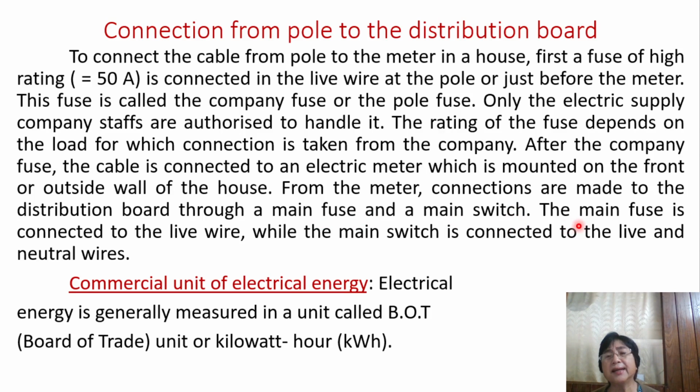And how are they connected? Please listen to this carefully. The main fuse is connected to the live wire. Main fuse to the live wire only. Okay, but the main switch is connected to the live and the neutral wires.